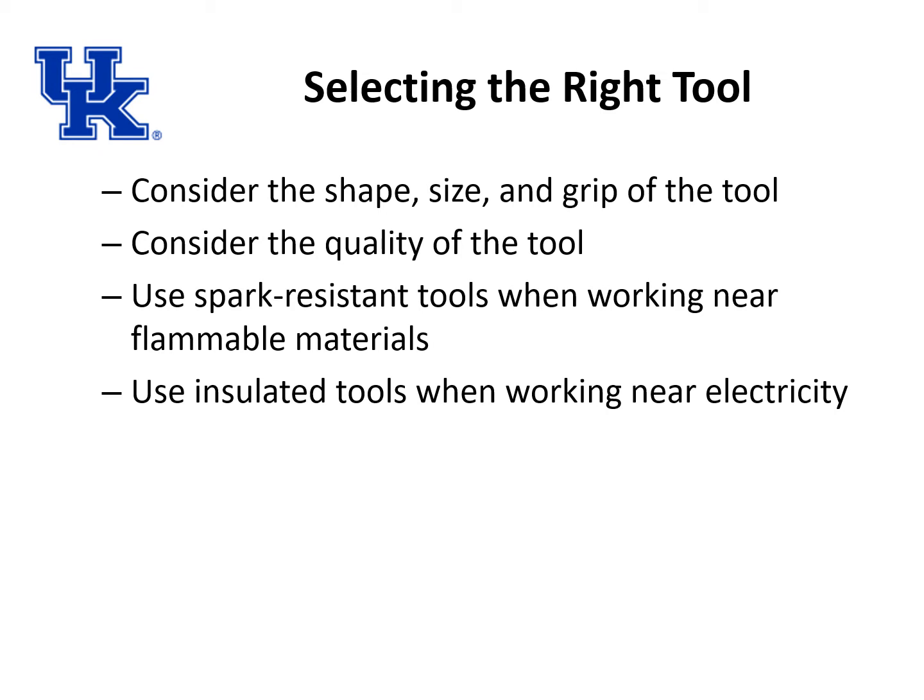And use insulated tools when working around electricity. Select tools that are rated for the voltage you will be working near. Also, do not work on or near energized electrical equipment unless you are properly trained.